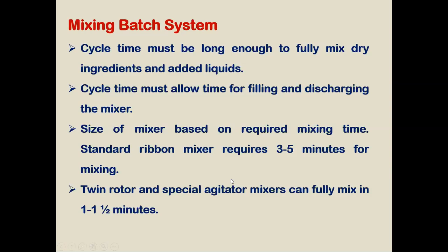The size of the mixer is very important, which determines the mixing time, the ribbon size, as well as the number of ribbons present in the mixer, by which the different ingredients are mixed. A standard ribbon mixer requires 3 to 5 minutes for mixing. This is the standard time under a standard ribbon mixer.